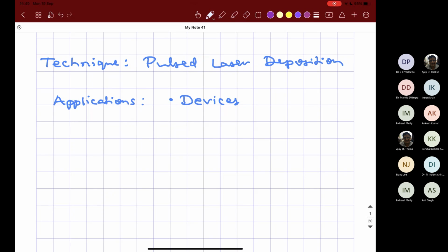But anyway, getting back to the idea. Silicon technology has really reached bottlenecks, and one of the bottlenecks is the thickness of the dielectric layer. Therefore, high dielectric constant materials are required so that even with a slightly thicker film, you can achieve a similar task. For that reason, we have to move beyond silicon dioxide. So pulsed laser deposition is one technique which allows you to make other oxide based dielectric materials. That is one of the applications.